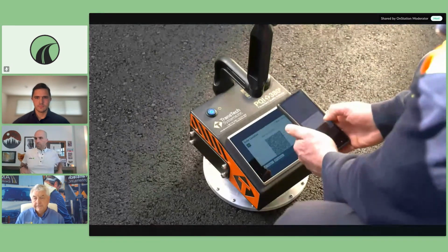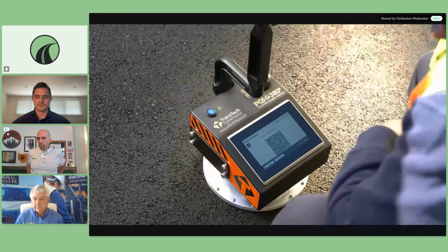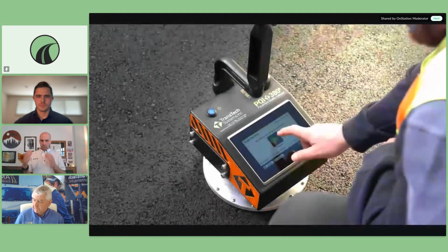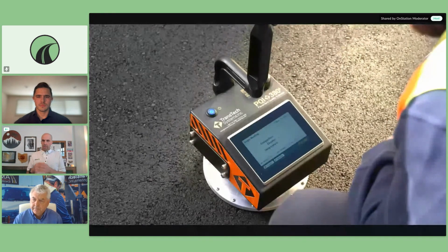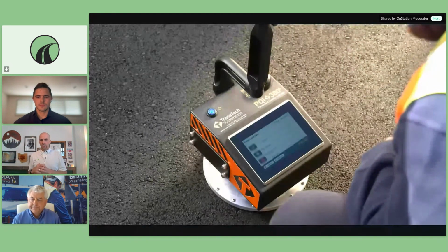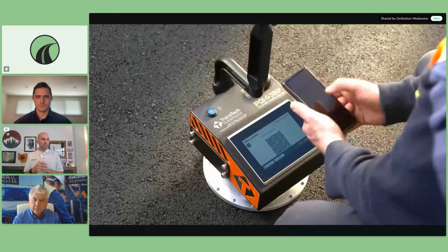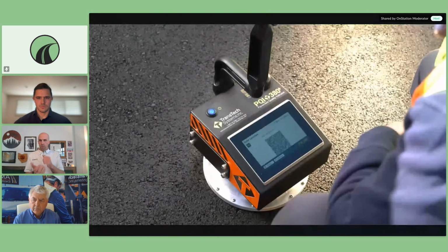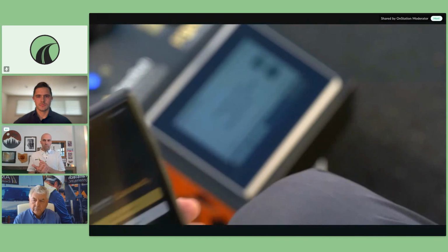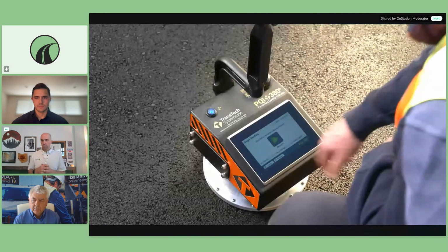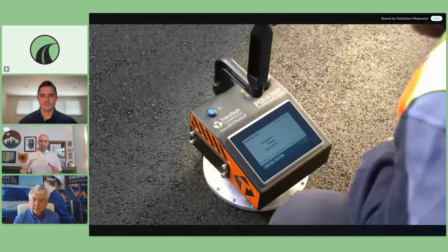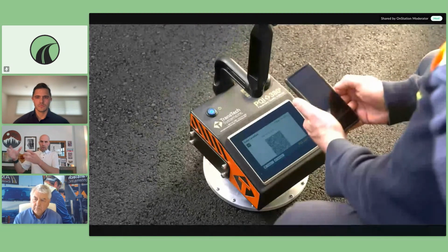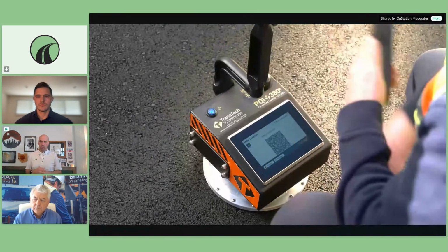He's going to explain a little bit more about the mechanics of the integration. Hey, Jake, can I just add something real quick before you start? Yep. So just to explain the connection here: your 380 Plus, your 380, and sending those test results into Connect. When you transfer those over to OnStation, we put that station alignment and offset on the test. We put that location, we stamp it on there because every test needs to know that location. And so if TransTech is capturing that data digitally, well, then it can flow to OnStation digitally, and we can create that record for you at the location on the project.